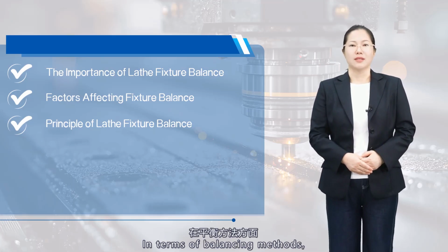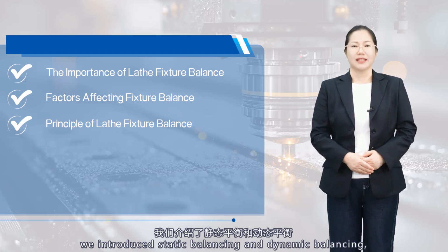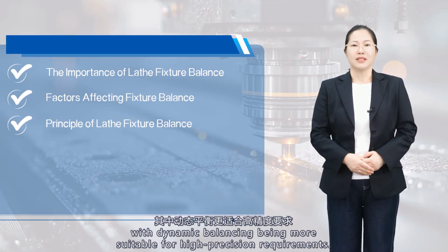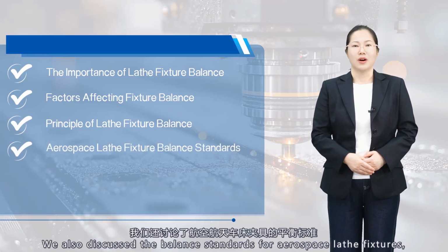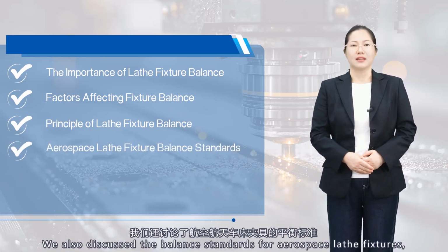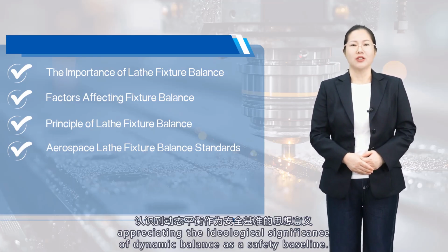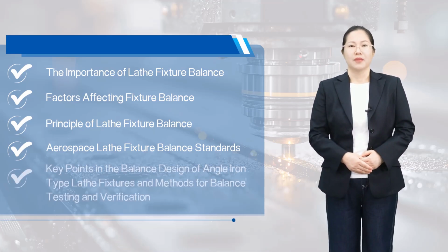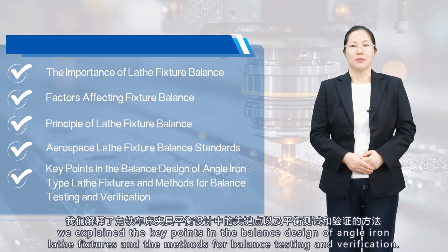In terms of balancing methods, we introduced static balancing and dynamic balancing, with dynamic balancing being more suitable for high-precision requirements. We also discussed the balance standards for aerospace lathe fixtures, appreciating the ideological significance of dynamic balance as a safety baseline. Finally, we explained the key points in the balance design of angle iron lathe fixtures and the methods for balance testing and verification.